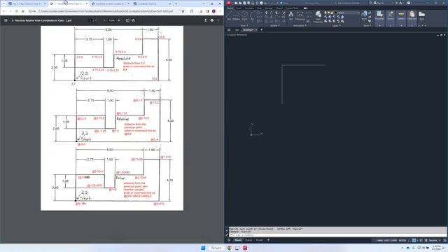All right, and I have a good example of this. So here was the practice worksheet that we did together in class. Each shape is exactly the same size, but we have different methods of plotting the points of each corner. So at the top, we have the absolute input. So we have a start point at 2, 2. And then you'll notice that our coordinates changed based on how far we go up and down or left and right. So from 2, 2, we go up 2.5, which means our y value needs to increase 2.5.